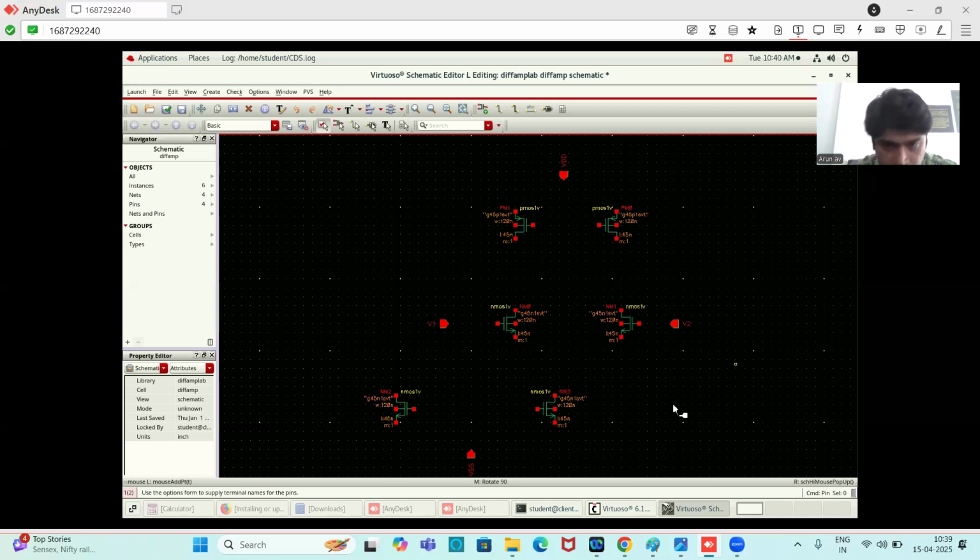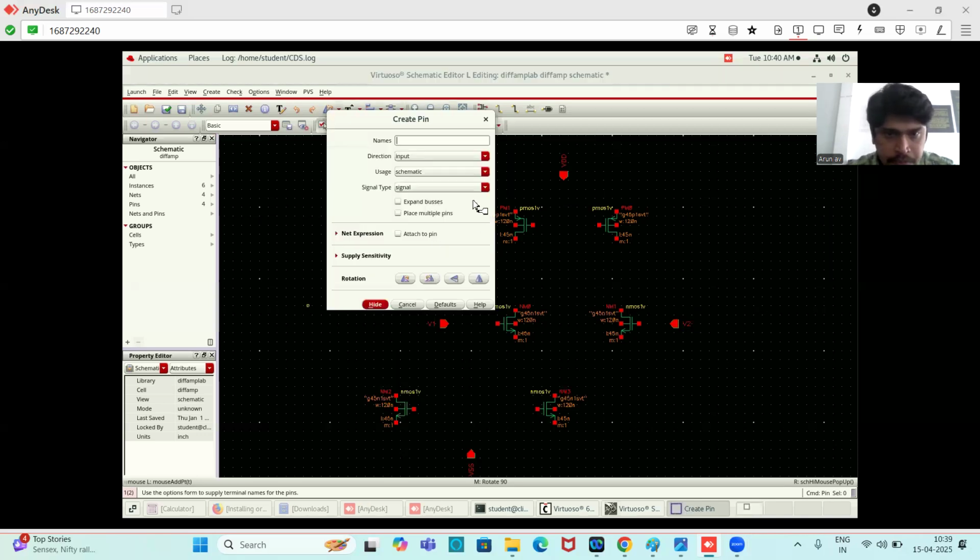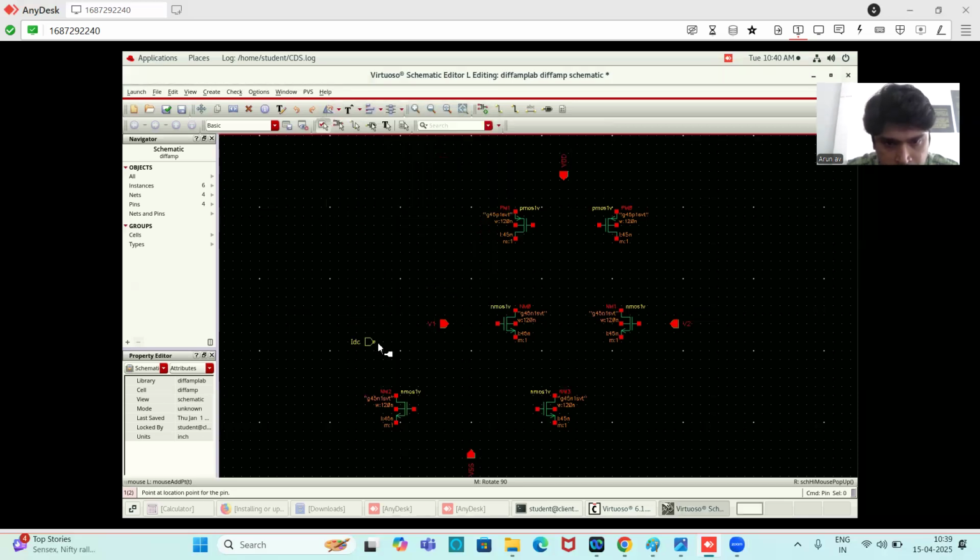Now, one more thing is that we need IDC, the bias current. So for that, again P, IDC. Okay, rotate it because this IDC should come onto the drain of this NMOS transistor. So I'm keeping IDC here.